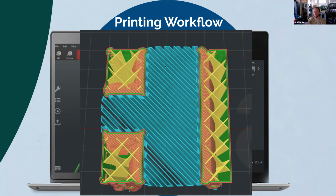Somewhere above this particular plane, this material is going to have to bridge and meet this material, but it needs something to build up onto, right? You couldn't just span this whole thing without the filament drooping or not attaching. So this support material is going to give it support as it bridges this. And then you can peel this accordion layer away, so you're left with a hollow part here, and supported material that spans from here to here further up in the part.